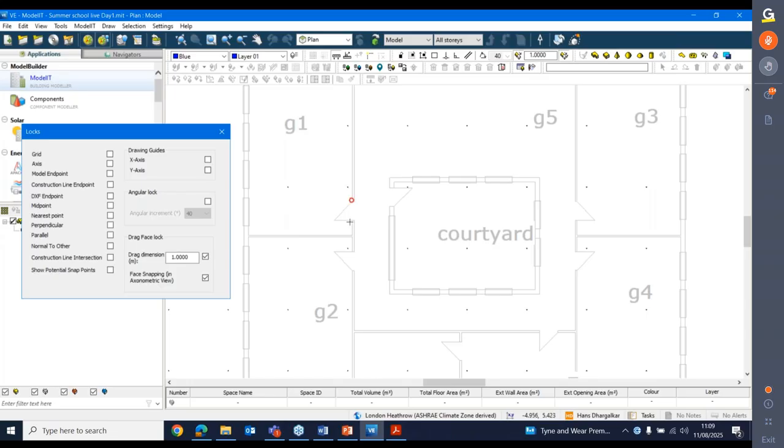That's a good tip. Measure something typical in the drawing and see what you get up here. So that doorway says 0.35 meters, which is obviously wrong. So it's obvious I've attached that drawing at the wrong scale.